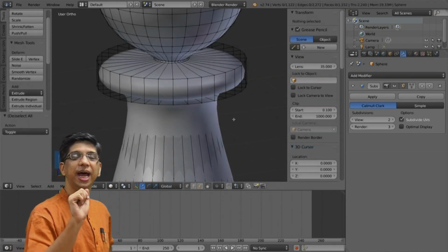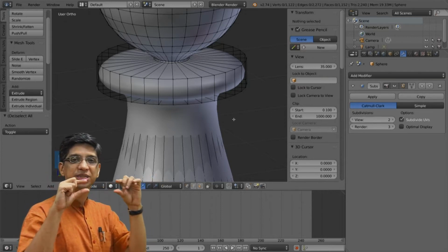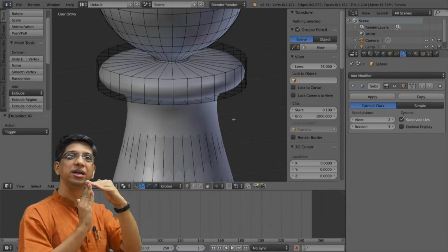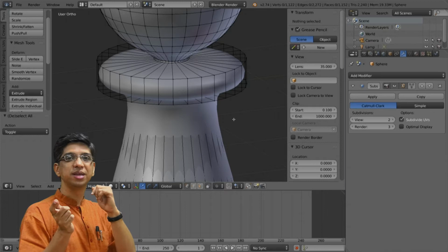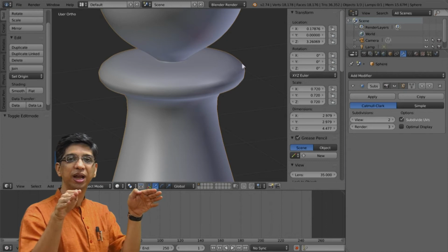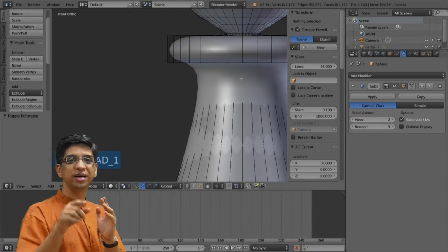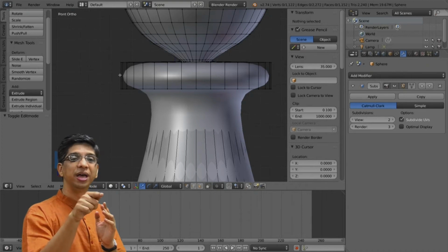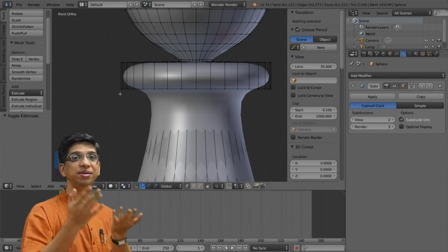You can see here that the cylindrical layer just below the globe has a very sharp edge. It is a right angle disc, we can call it a disc. However, when we apply subdivision surface, the model becomes very smooth and there is no right angle existing right now. Even if I go to front, you can see that the edge of this chess pawn has become very curved instead of the right angle one which was modeled earlier, because we have applied subdivision surface.